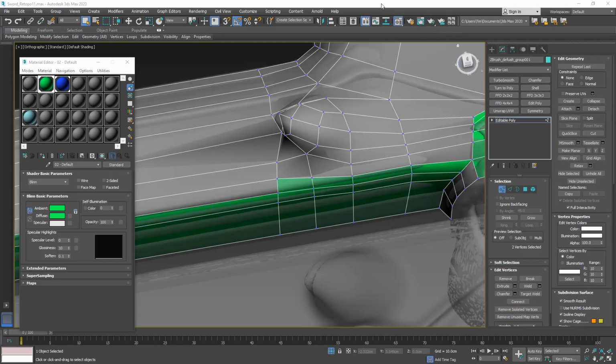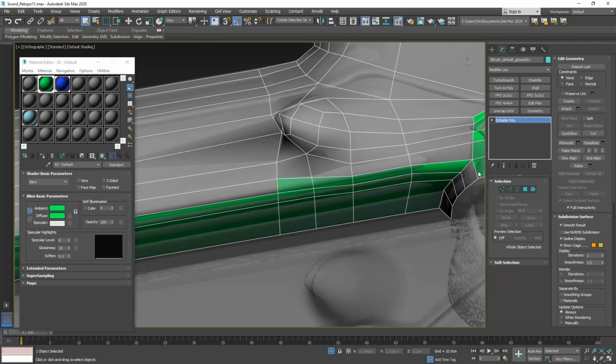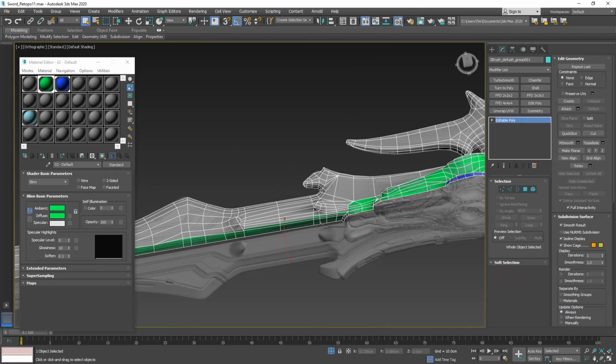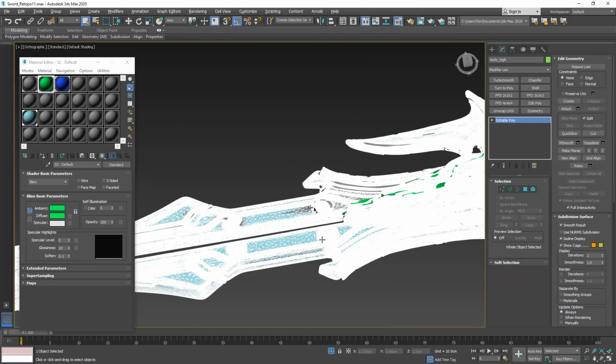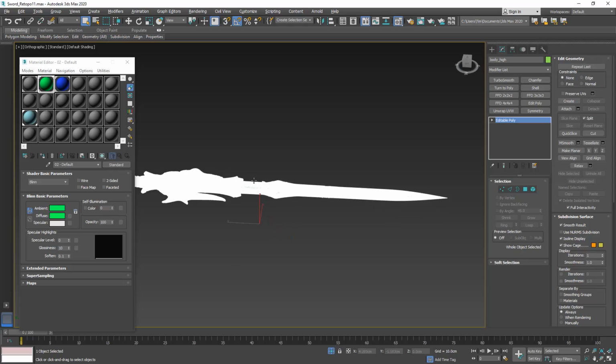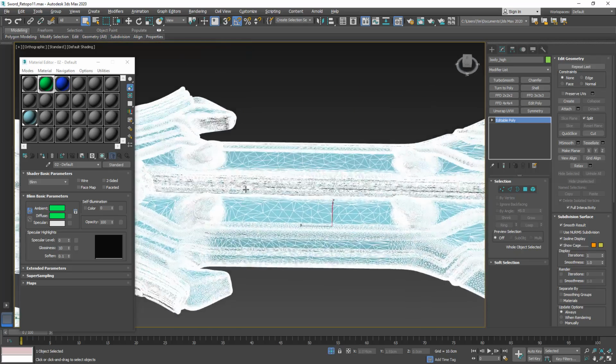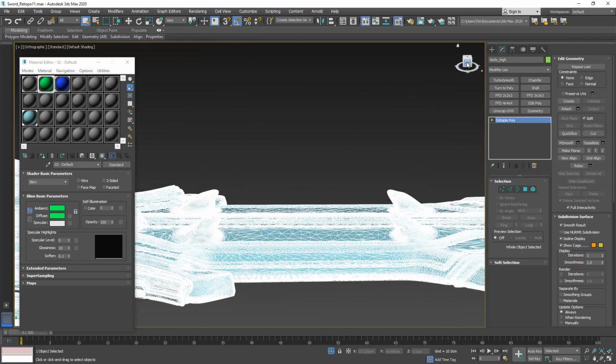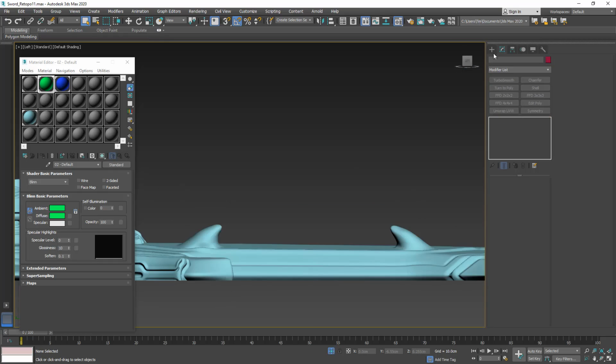So before we do any further work here on that blade, I actually want to be working on these little knobs that are sticking out of it. And for that, I'm gonna select our high poly model, take it into isolation mode. Before that, I had it in transparency mode, so just make sure to press Alt X on it so you see it without transparency as a solid material color here.